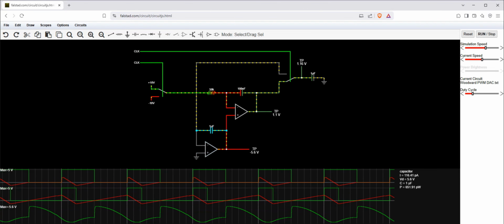The reference is an LT1021 5V buried Zener that I happen to have on hand, doubled and inverted using some high-quality 0.1% Chinesium 0805 resistors and an OPA2140, another of which also serves as the PWM and sample and hold integrator. The PWM and sample switches are two halves of the TMUX6136, a precision low leakage low charge injection SPDT analog switch from Texas Instruments.